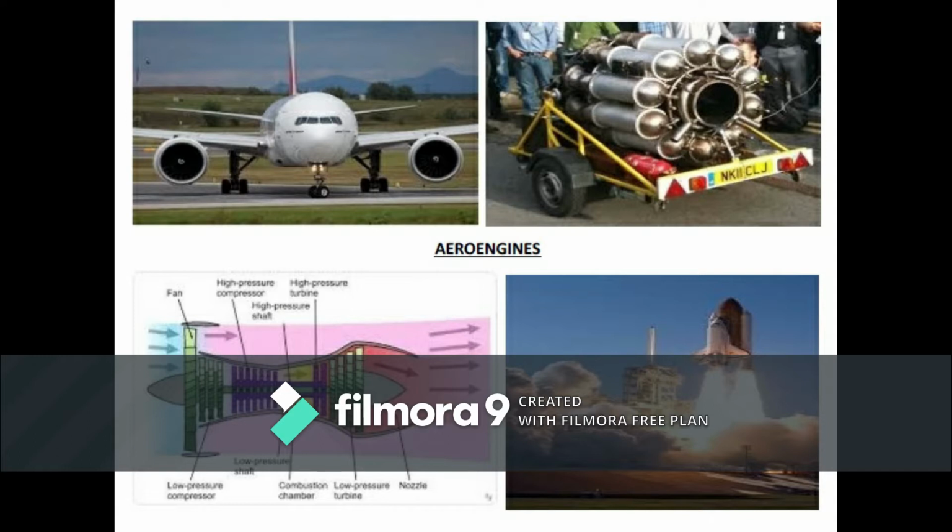Each has its own merits and demerits, advantages and disadvantages. The pressurized air is taken to the combustion chamber, where fuel at high pressure is injected into the pressurized air, and both get mixed together. Ignition then takes place, and combustion occurs at high pressure. Those high pressure hot gases will move rearward, and after the combustion chamber there will be a turbine.